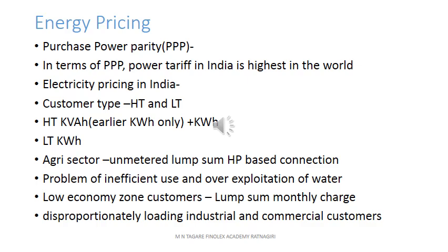They have implemented, instead of charging kWh, that is active energy, and power factor, they have started considering apparent energy. Now, how do you reach apparent energy? We know the power triangle: one side is active power, the second side is reactive power, and the third side is apparent power. And we know S is the square root of P square plus Q square. Now this is in terms of power.